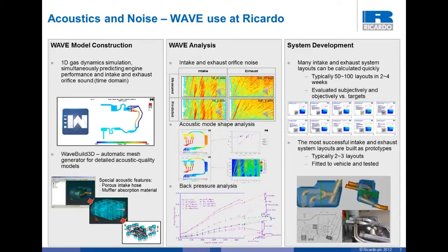It's all very well doing NVH and making a nice quiet engine, but if it just compromises your performance and back pressure, that's no good. So that's another excellent use of tools such as Optimus, where you can put a constraint in your back pressure targets over the entire exhaust system or individual components such as a muffler, and do the trade-off on meeting your sound pressure levels, the intake and or exhaust, and making sure you do meet those constraints on your back pressure targets.